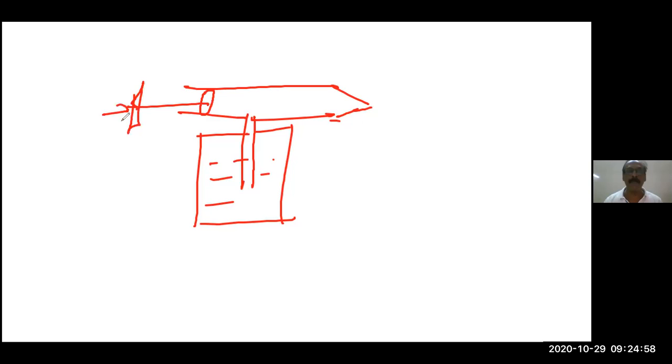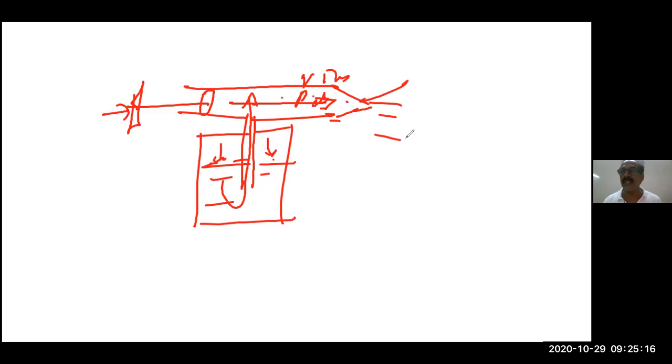Now, when you push the piston, air will flow here, so velocity increases and pressure decreases. Velocity increases inside, pressure decreases. From the other side, atmospheric pressure is more, and that pushes the fluid here, so it will be sprayed out. This is how perfume and everything works. When you press, that area's pressure is reduced, the liquid comes there and is sprayed out. Is it clear? Yes, sir. This is the atomizer.